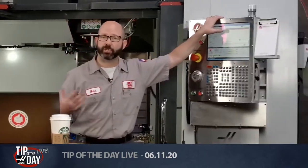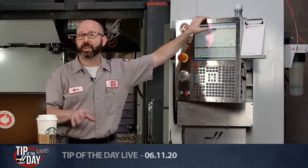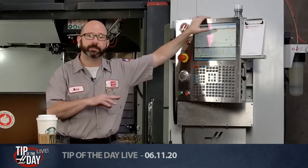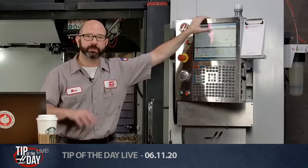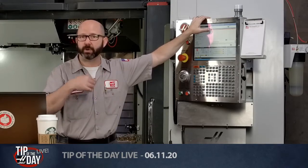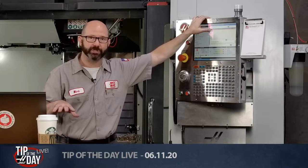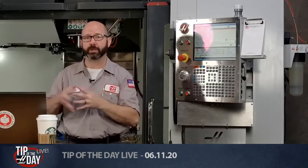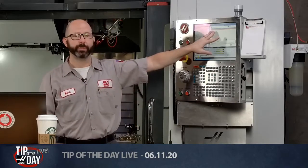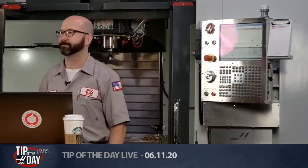If you didn't catch that a minute ago about the settings on the machine, the question was, is there a way to avoid a tool change at all costs? On the next-gen control, you can go to settings, do a search for tool changer, and you'll find setting 113, which is typically set to automatic. You can see it do a tool change. If you set that to manual, it's not going to do a tool change on you. So if you have some funny, goofy tool that you don't want to run on your tool changer, you can change setting 113 to manual, and that's going to avoid tool changes at all costs.